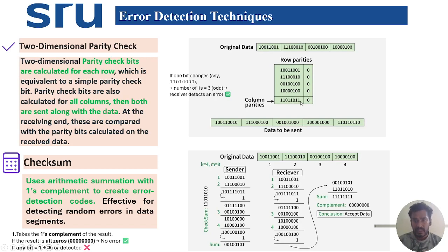Finally we need to count the sum of the data bits column-wise. Here two ones appear, so we directly put a zero, and the remaining ones appear here again. Then we count here, one, and here also one. Here two ones appear, so put a zero to make it even. In the case of here there is one, so directly put one.